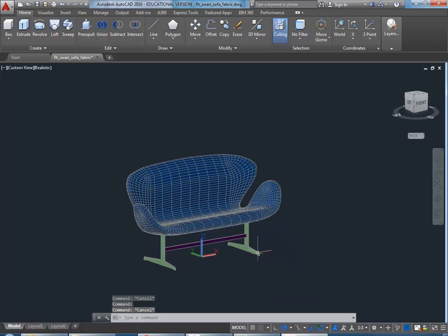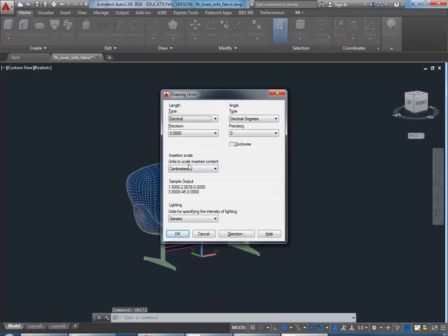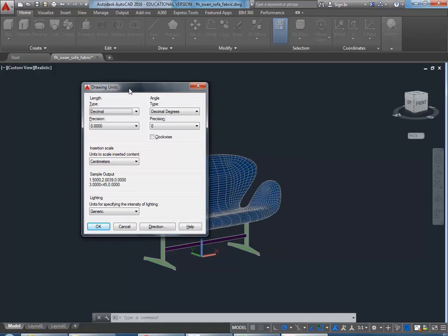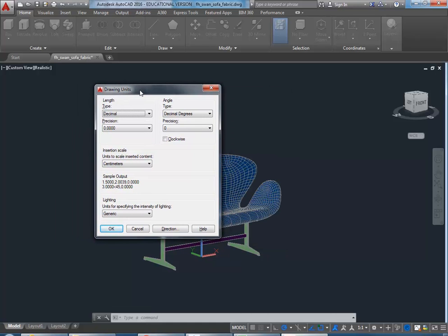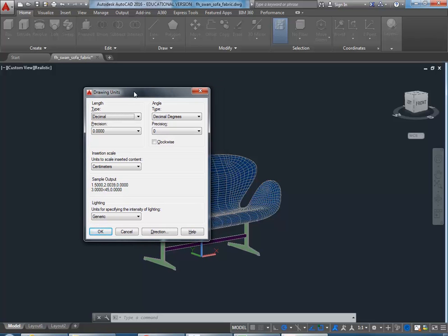So I'd say it is inches, even though the person who's set it up has then gone and set it up to import in centimetres. And that's one of the common misunderstandings with AutoCAD. AutoCAD actually doesn't, unless you get into these kind of secret settings that Architectural Desktop uses more than AutoCAD, have a real units setting. Units are what you decide they are. There's a unit in your AutoCAD file, and you need to decide whether that represents an inch or a centimetre or a millimetre.